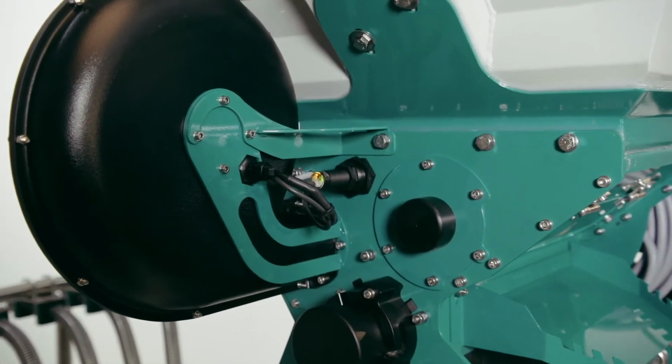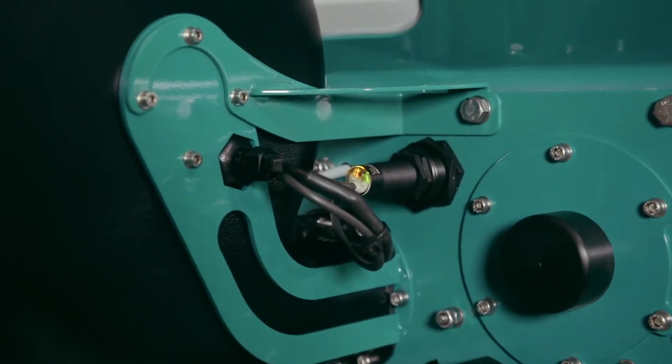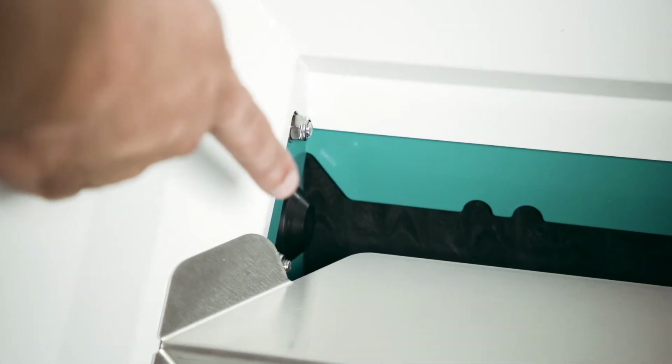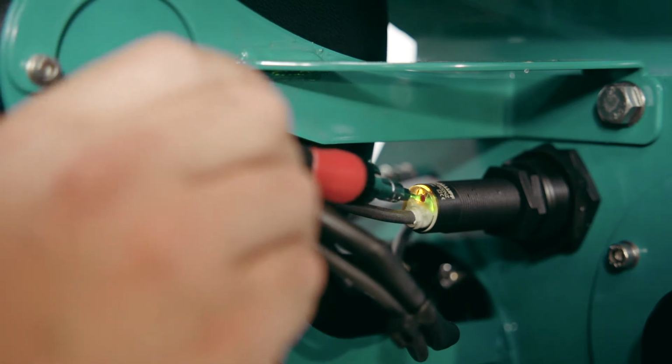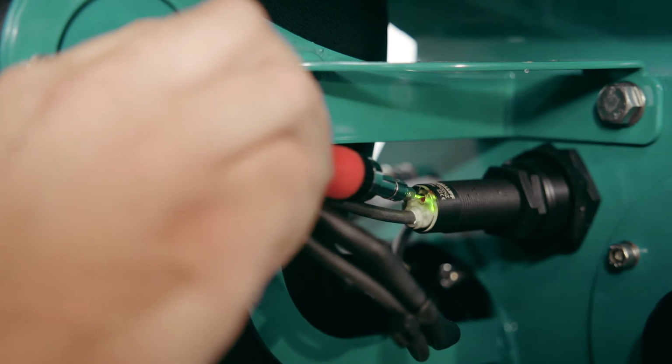The LED light for indicating hopper empty is located beside the blue fan button. When the hopper is empty, the orange LED light switches off. The sensitivity of this indicator can be adjusted to prevent incorrect function when using materials depositing dust residues.